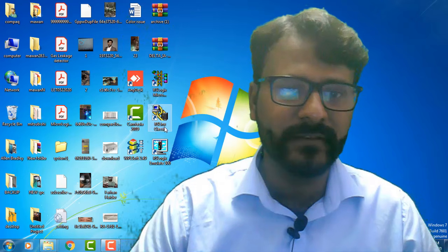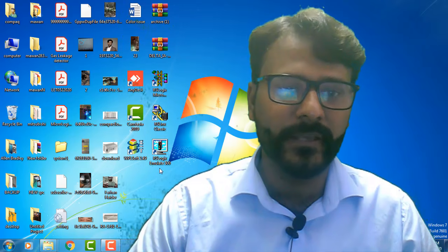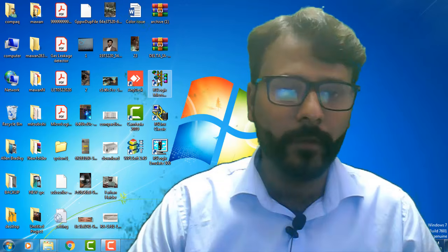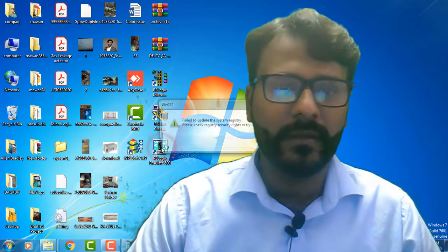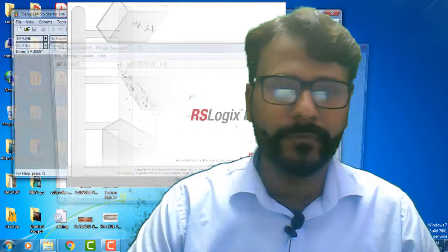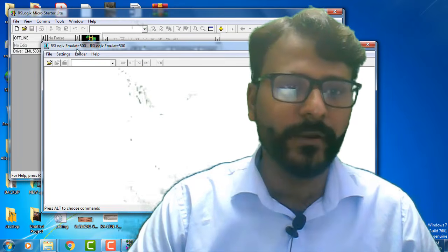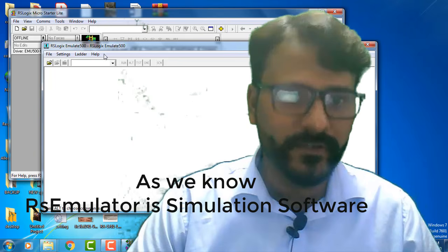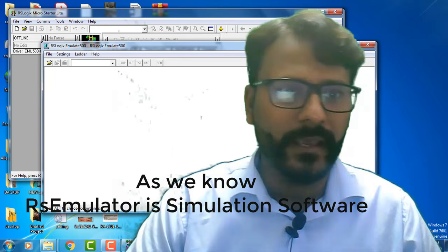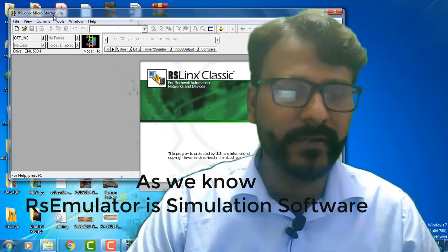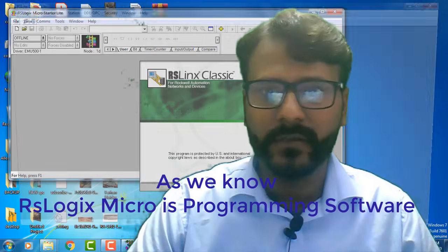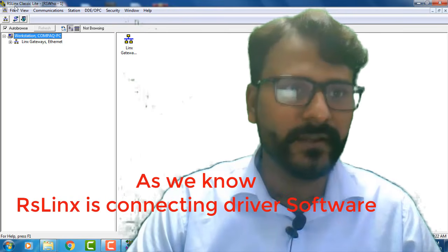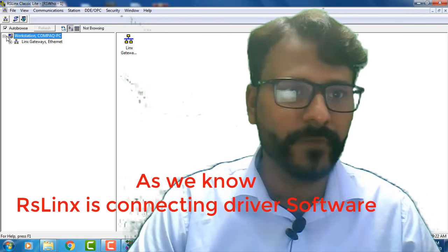RSLogix, RSLinx and RSLogix Emulate. So we will open 3 software at a time. As we know, RSLogix Emulate is a simulator software, and RSLogix Micro Starter is a programming software of the embedded PLC. And the last one is RSLinx Classic, which is a driver software.